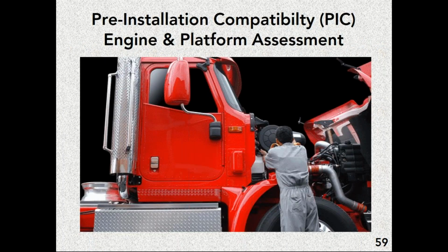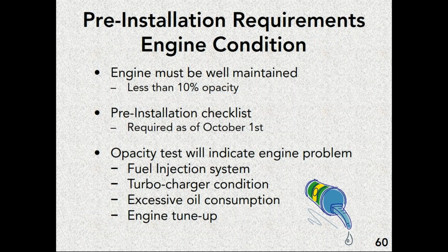Before you do the retrofit, you do need to do a compatibility check with the engine. This is an assessment to determine whether or not the engine will actually accept a filter properly, and whether the manufacturer of the filter will actually allow you to install it on that engine. The compatibility check is going to do several things.